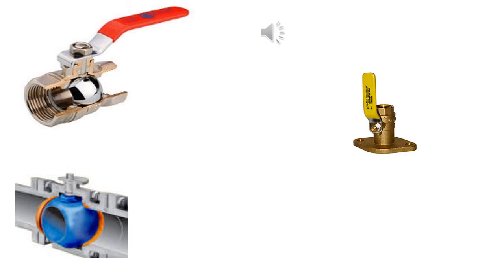For example, a 2-inch full port ball valve will be compatible with a 2-inch pipeline, and it will have a 2-inch valve opening inside the ball. This is great for applications that require very little to no flow loss.